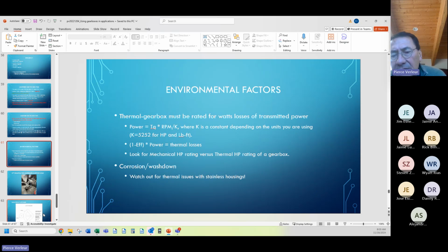And if you get condensation, well, what does water in your oil do for your hydraulic system? Not good. What about water in your oil in your expensive car? Again, not good. Same thing here. You gotta watch out, especially in washdown applications where you have high humidity, therefore your danger of condensation is even worse. And if you don't design your seals properly, you get weeping going the other way when you hit the output shaft seals with 100 psi of corrosive water.